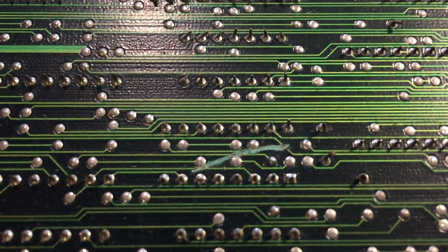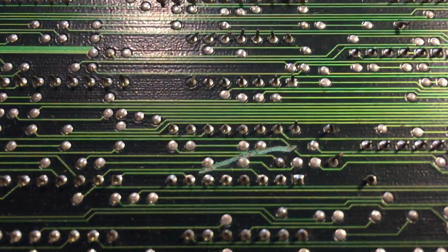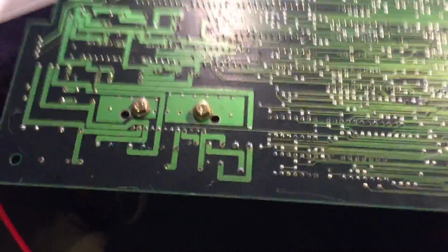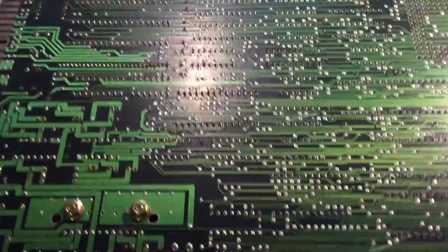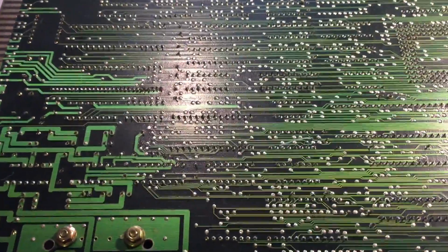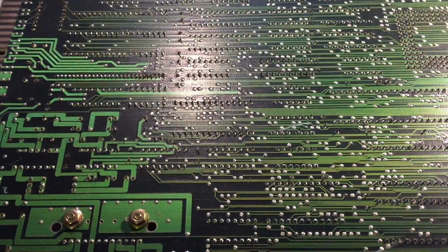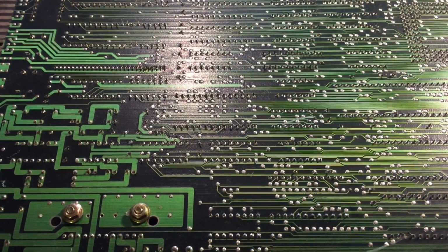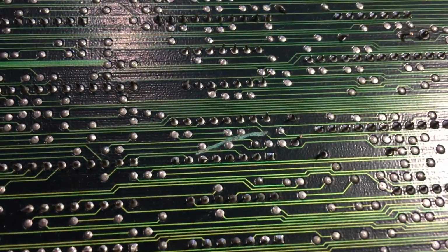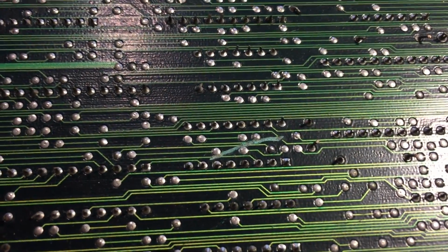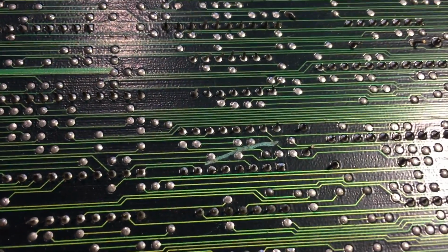So I'm going to check that with a continuity test and see if there's any lines there that need to be repaired. That may not solve the interface IC connection problem that I have, but if there are bad connections here, they've got to get fixed too. So let me measure those out and see what we need to do. Well, I've definitely got bad traces here, so I'm going to have to patch those up.